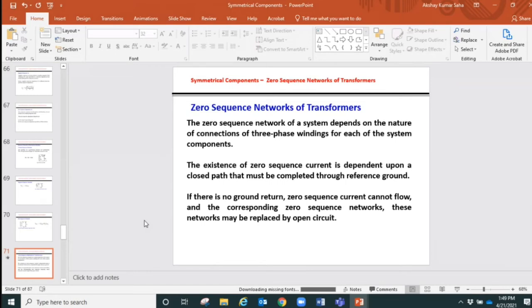So if you have a 5 ampere current in the secondary side, how many amperes you will see on the primary side will depend on N1, N2 or V1, V2 for the rated voltages of the transformer. So we'll see that reflected component of the secondary winding in the primary. In the primary we still have that no load current I0. So these two currents are now added vectorially and give the final value of the primary current.